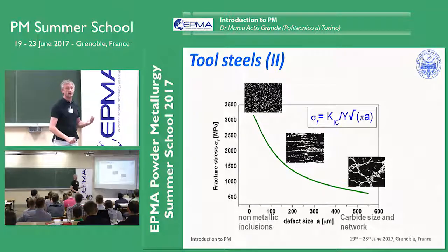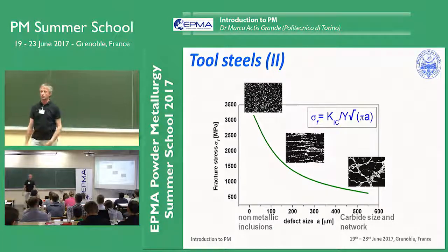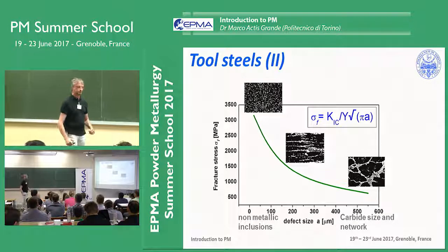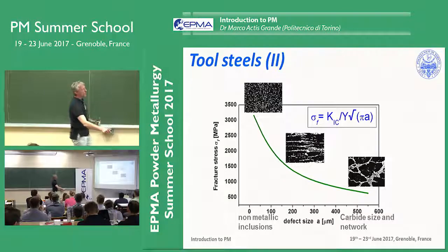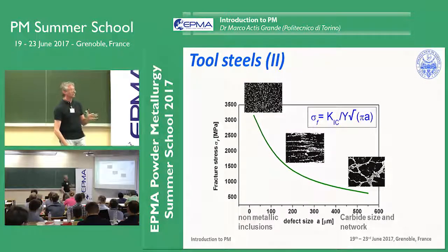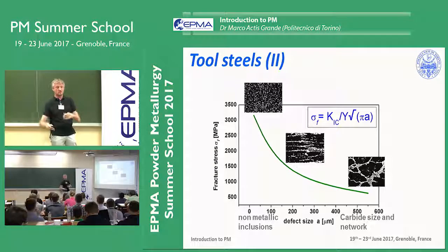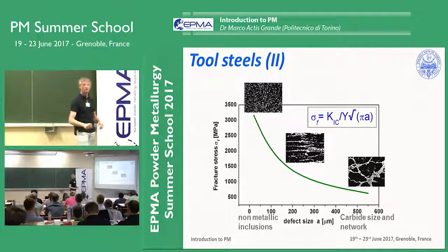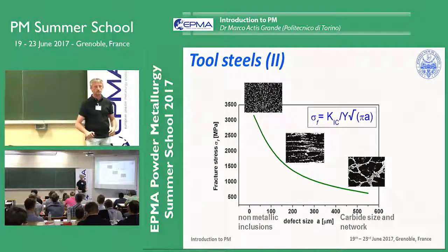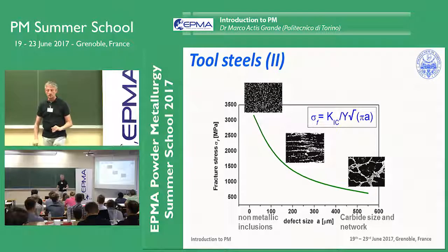What is this resulting in? Well, in terms of mechanical properties, everything is referred to mechanical properties. Who cares about these mechanical properties? Yeah, they are important, unfortunately. We are engineers, so we have to remember that they are important, somehow. So, what is this? Well, actually, we can refer to a carbide like a sort of defect. How are they distributed? Well, they are distributed in a way which is somehow more homogeneous, more regular. What is this resulting in? An improvement, of course, a potential reduction of elongation at rupture, but a much higher tensile strength, or in general fracture strength of the component.